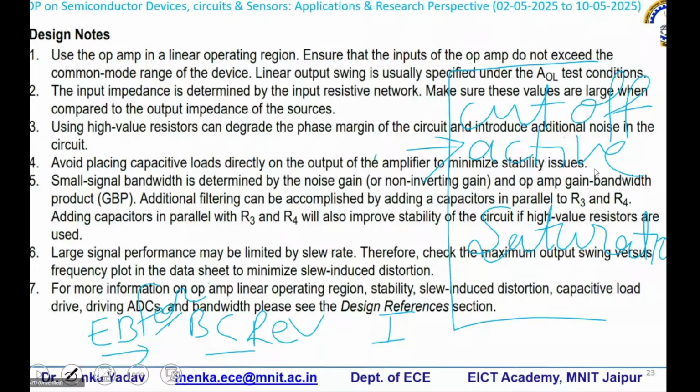So how will I get that? I'll make sure that my input is greater than VTH, and at the same time VDS is also greater than VGS minus VTH. That I'll make sure. And if you make sure of it in this way, then you can proceed further.